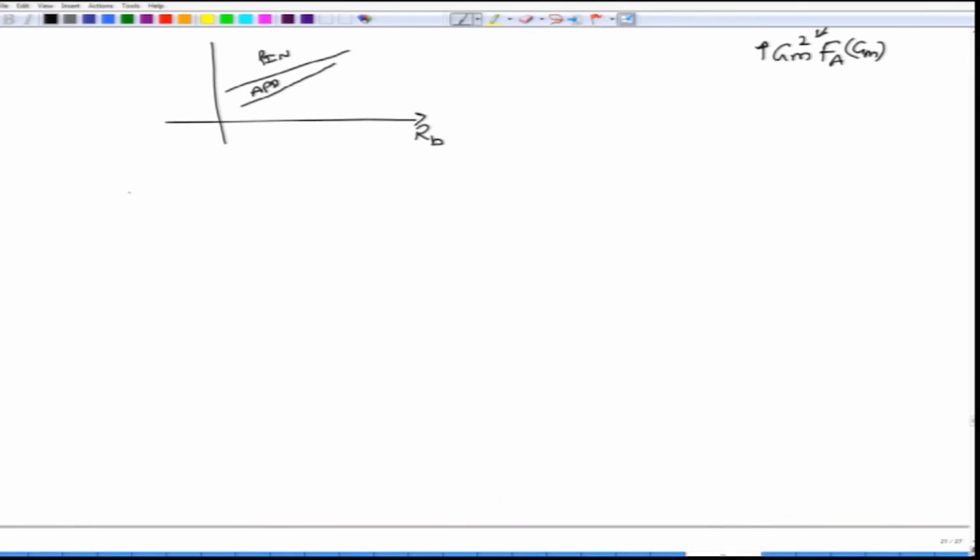Moving on to the next case where you have an optical preamplifier. In the optical preamplifier case, what would be the major noise factor? Well, it is the signal beating with the spontaneous emission, which is the major noise factor. This would be the case when you have transmitted bit 1. For bit 0, you have thermal noise, you have spontaneous noise, as well as some amount of shot noise. Shot noise is actually equal to 0 because you have transmitted bit 0 here.